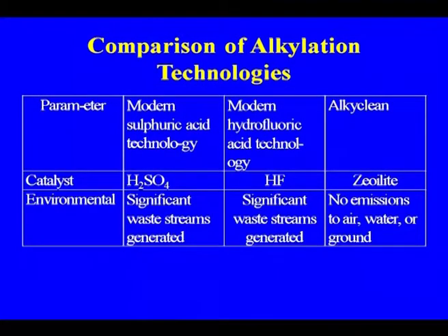For the catalyst, here we are using the zeolite catalyst, with environmental significance. If you compare HF and H2SO4, the amount of HF required is much less than what we use in sulfuric acid alkylation. This was one of the reasons for shifting from sulfuric acid to hydrofluoric acid alkylation. In the case of the solid acid catalyst, there is no emission to air, water or ground.